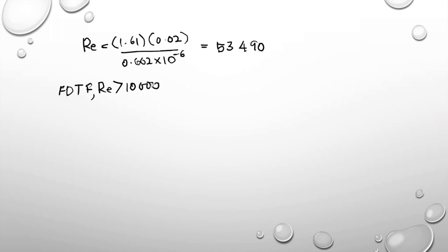So under fully developed turbulent flow, we know that the equation is only one. Okay, Nusselt number equals h D over k, equal to 0.023 Reynolds number to the power of 0.8, Prandtl number to the power of n. Okay, this is the equation for fully developed turbulent flow.